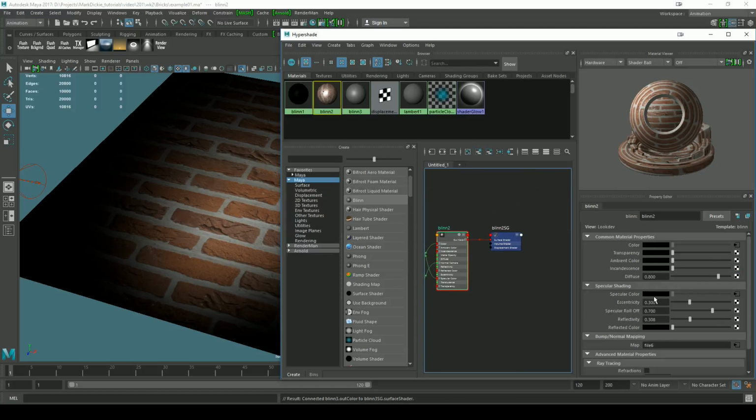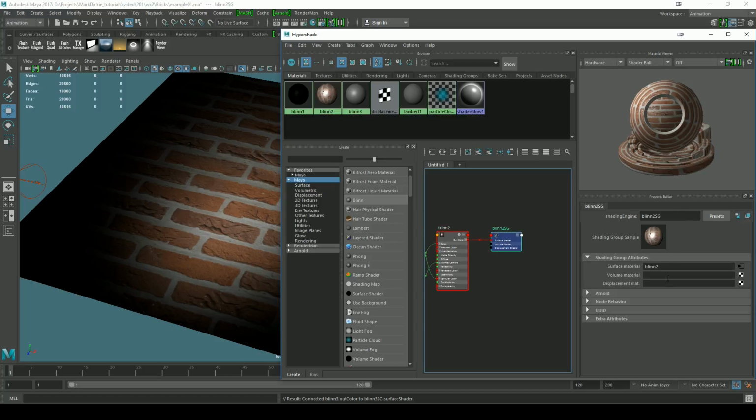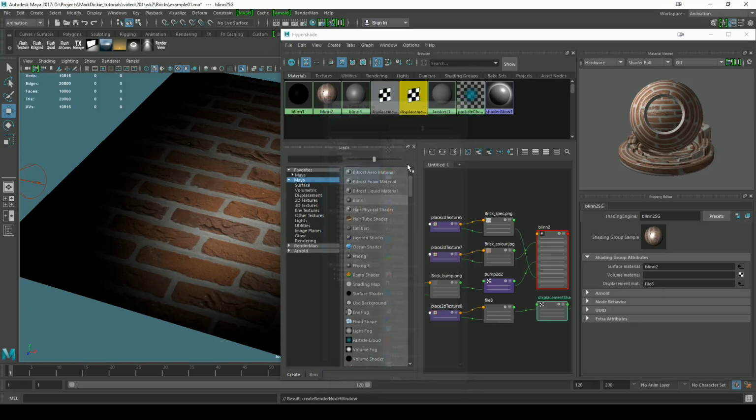With the blend too, so we've been working with all these settings. The final one is actually the shader group. So this blend comes into the shader group, and it's this displacement map. So again, this won't do anything in the real-time renderer, in the viewport. It will apply the displacement at render time. So I'm going to click here, once again, load a file.